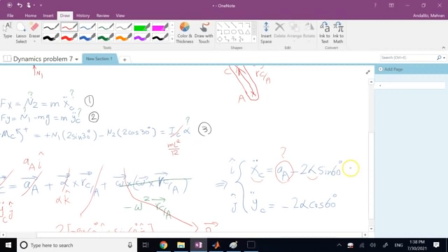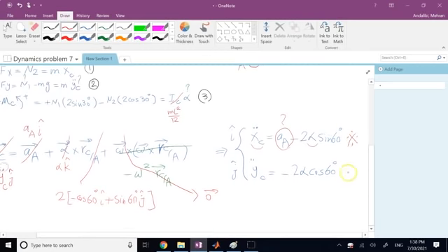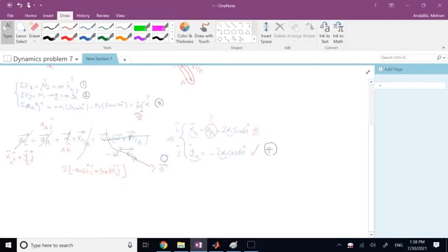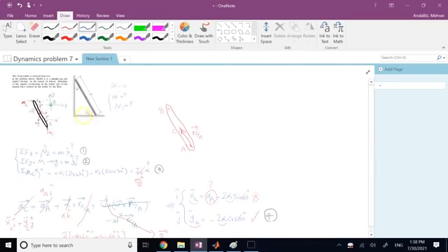So this one is definitely not something you want to consider, because it's not helping. It makes your 5 unknowns 3 equations, it makes it 4 equations, but makes it 6 unknowns. So it's not helping. But the bottom one does. The bottom one directly gives you y double dot of c in terms of alpha, so it doesn't introduce any new unknown, but it adds one more equation. So this is going to be my equation 4, and I do not use the top equation. So here I found one more equation, and I use the constraint that A has to move horizontally.